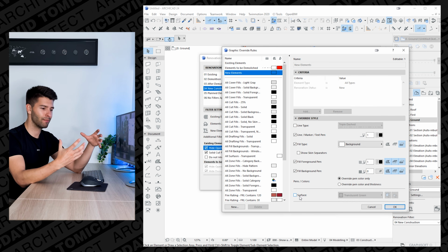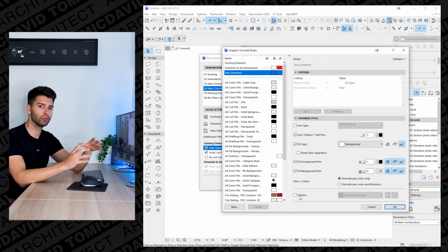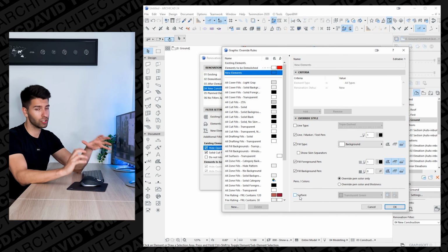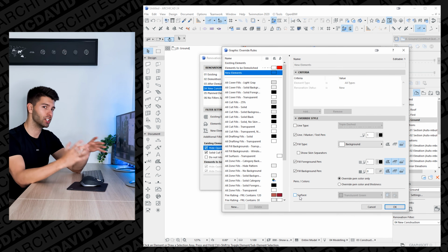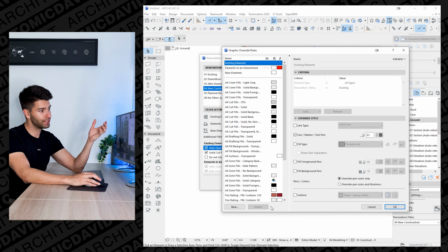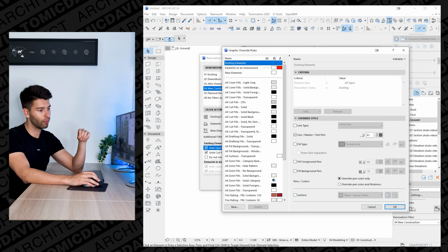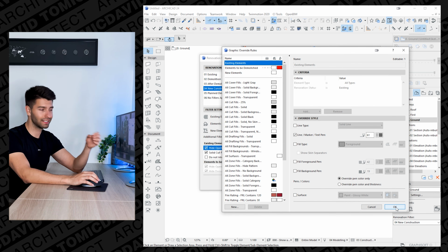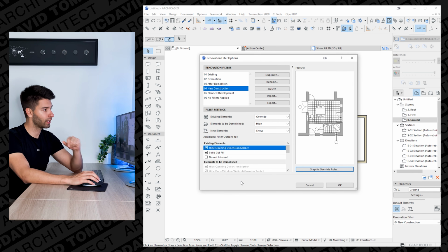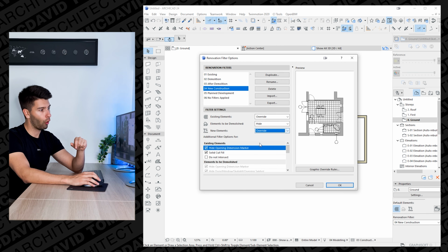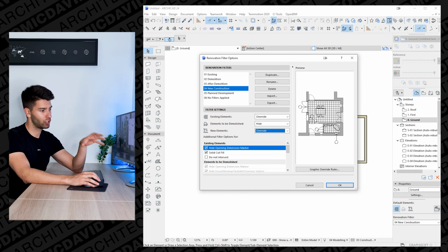If you're doing a 3D massing model, for example, and you just want simple shapes and colors, that is a very quick and easy way to adjust all of your new construction surfaces without having to change everything individually, then changing it all back. Personally, I'd go into existing elements as well and untick that like I said before, so we don't have two different color material palettes working against us in a new construction. So clicking OK there and going into new elements and overriding that, we'll see all of our elements have changed.